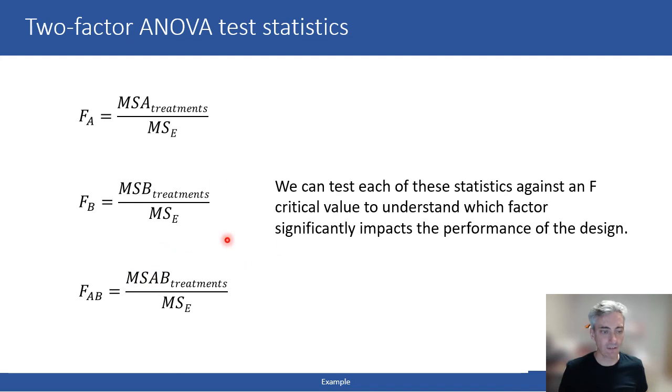By combining this knowledge with the main effects plots, we can actually build an empirical model to predict how the system behaves. For example, how the roughness of the 3D print depends on the different factors and interactions. In that model, it would only be necessary to include the factors which are significant. In other words, the factors which have an F value greater than the critical value. Because for the other ones, the statistical test tells us that it's just not worth considering. It's insignificant.